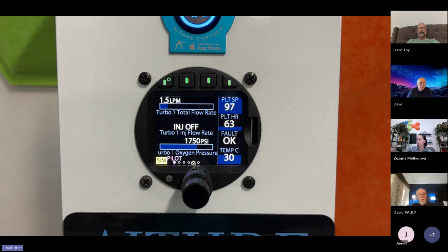I'm not going to cover wiring in detail, but I am going to just give you kind of a top level overview. The wiring for the HealthView 2 is pretty simple. There's going to be power and ground. The total voltage is anywhere from 12 to 30, and the total current at 12 volts is about 20 milliamps. It's very low power draw, not 1 amp, but 20 milliamps. And that would be identical between all 3 of the screens. That's screen and HealthView 2 data bridge combined.